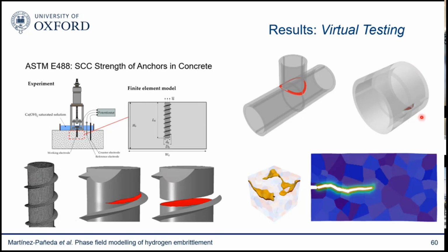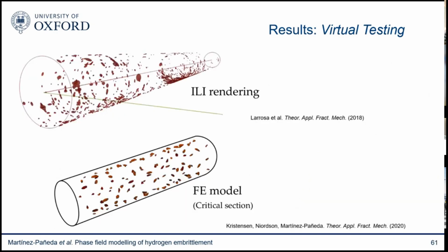But also you can go up the scale. These are continuum level finite element models, and computers are big enough these days. So you can handle pipelines, you can handle pressure vessels, any geometry that you are interested in. So you can finally bring this idea of virtual testing, which has saved billions in the automotive and aeronautical industries, to hydrogen-containing environments. And I think quite excitingly, because the model can deal not only with cracks but with defects of any arbitrary shape, we can eliminate conservatism, and we can basically deliver predictions for problems of arbitrary complexity.